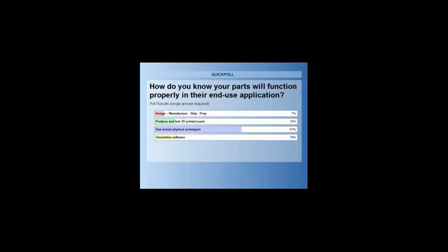Compression molding. No, flow simulation can't be used to model that, but that has been coming up quite frequently in our plastic injection molding software, so you could potentially do that. Can I set up Excel to drive an automated optimization? You wouldn't use Excel. You could do design tables inside of SolidWorks, or basically our parametric study is an Excel file, so you could cut and paste the values from your Excel file and then use them.